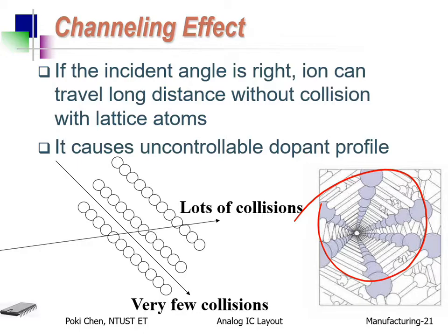Okay? So, what is the impact? If you look vertically down on the surface of the wafer, you inject your ions directly perpendicularly into the structure. What is the consequence? It will penetrate from the top surface to bottom surface. You can see, this is some kind of big hole, very deep hole.